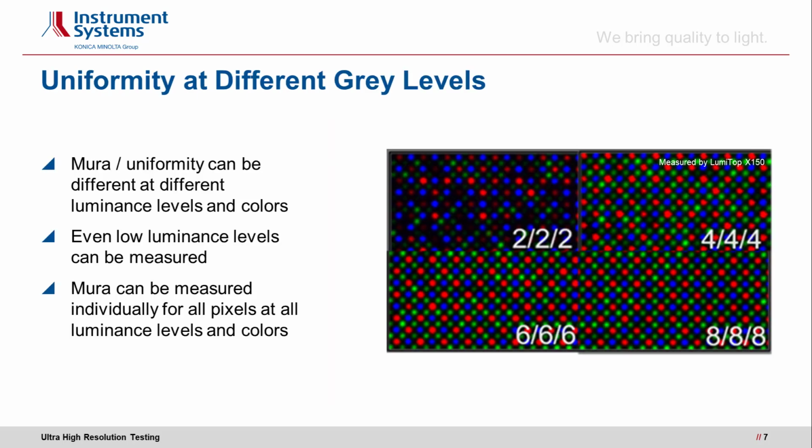The behavior of individual pixels varies considerably depending on the brightness level that it is set to. This is particularly true for very dark levels. The images shown on the right show the detailed behavior of individual pixels when the overall brightness of the display is varied. The higher the number, the higher the gray level, and the higher the overall brightness of the display.